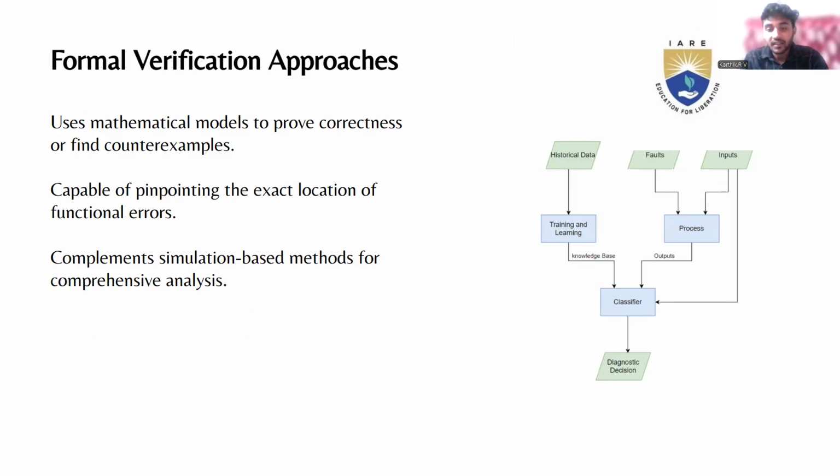Formal verification uses mathematical methods to prove correctness or to find counterexample errors, and it can identify the exact location of functional errors. It complements simulation methods.